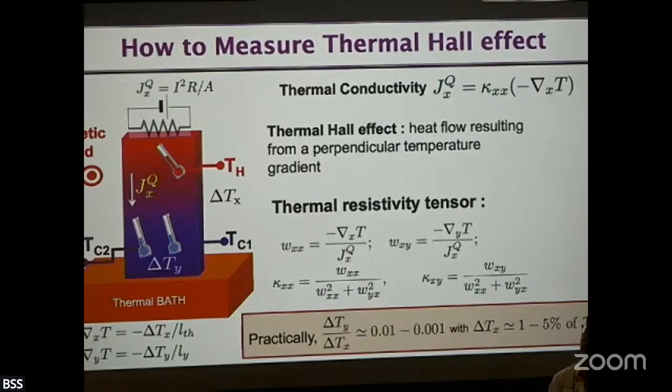From there, I turn on the heater and try to stabilize the temperature. For the electrical measurement, about 1 to 5% temperature stability is excellent temperature maintenance. But for thermal measurement, we need exceptionally stable temperature during the measurement.